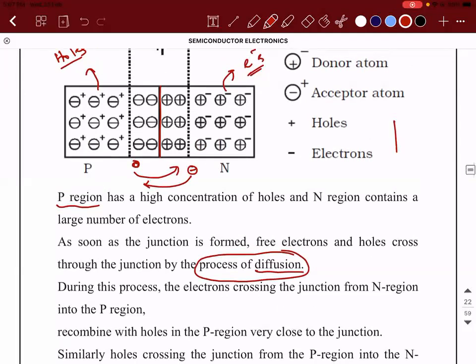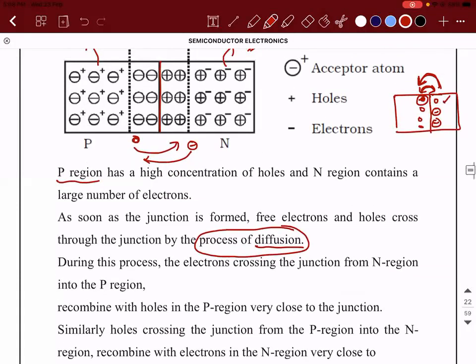The logic is very simple. At this junction, you have this P-type and this N-type. When the virtual positive and negative charges are closer to each other, the negative charge and the positive charge merge together. When the negative charge starts moving this side, there is a vacancy created where the negative charge was initially present. Then that becomes a hole and this becomes negatively charged. So this is the first step. Are you clear with what I mentioned? This is a very, very important point.